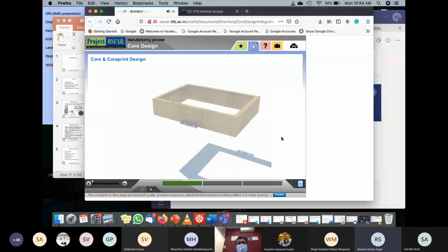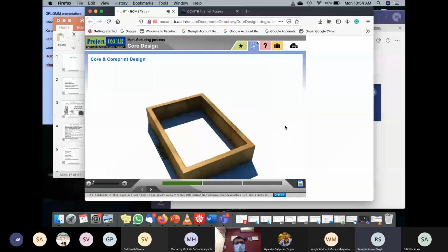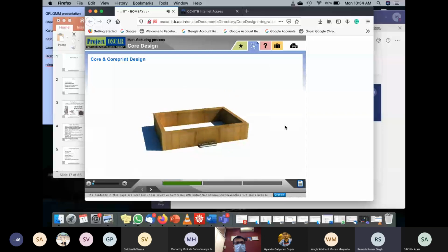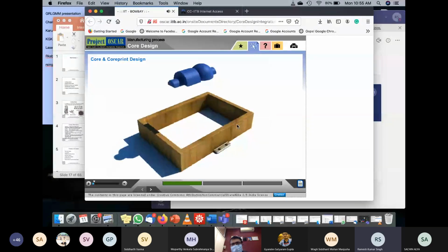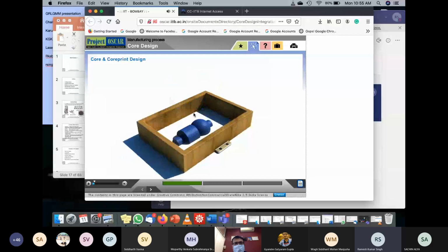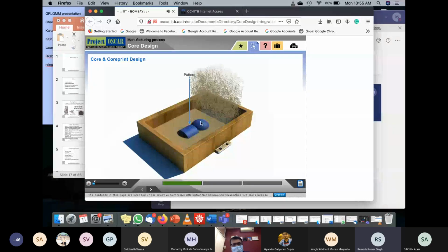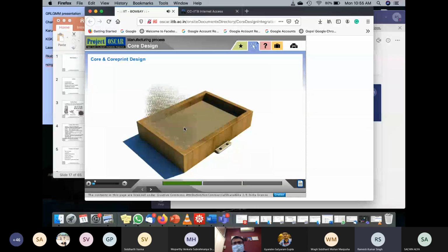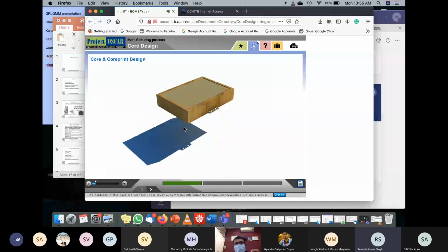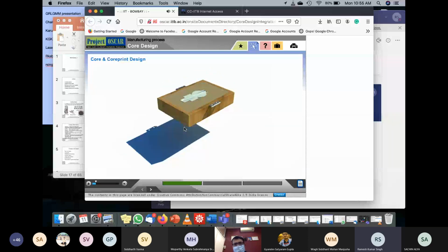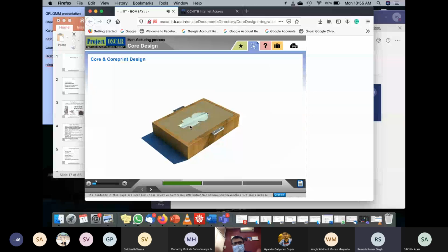To make a hollow metal casting, we require a pattern supported by a core and a core print. This demonstration provides a useful way of understanding the following steps. Take hollow boxes, rectangular in shape. One is called cope, one is called drag. As shown, this is the half pattern. So you'll put a ball there, half the ball there, and pack the sand and compact it. This sand will not be natural sand. This will be with the binder, so that when you pack it, this sand will become almost like a solid, right?